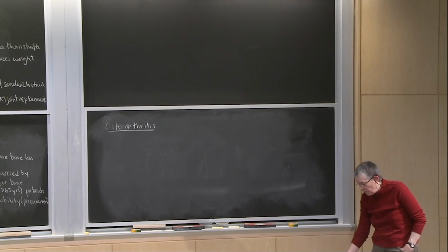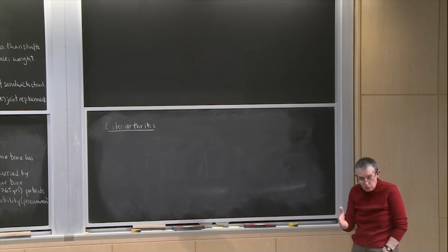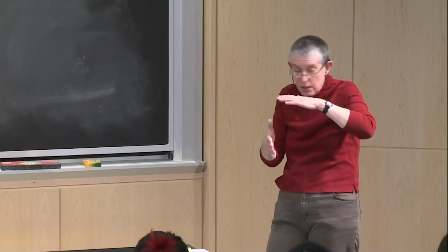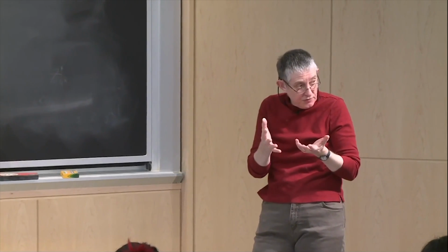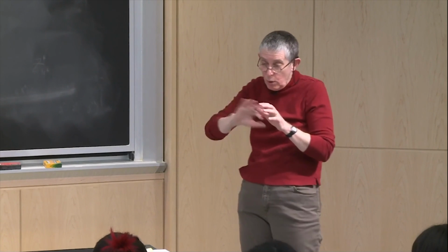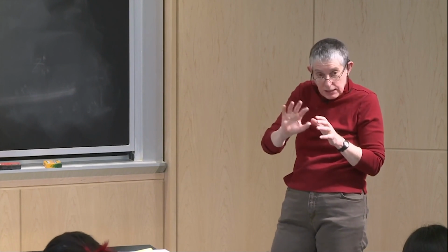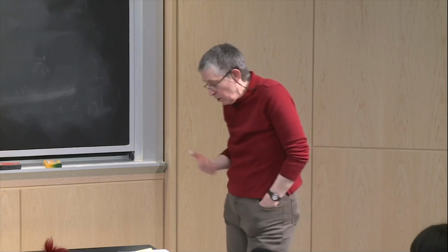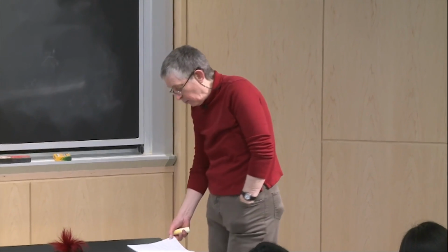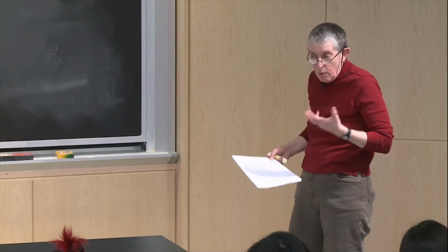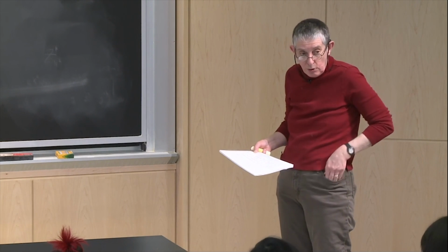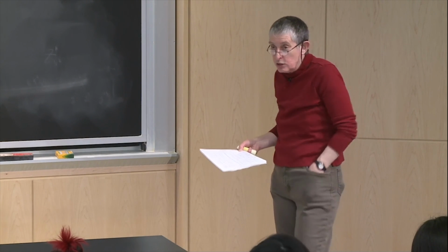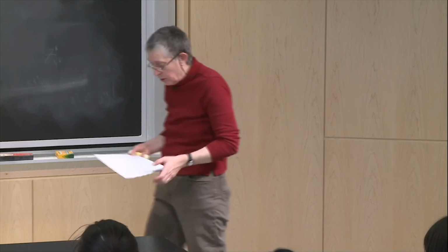You can imagine if you have a fiber composite, for instance, and you're loading it along the fibers, most of the stress is carried by the fibers because they're stiffer. So if you have bone, like trabecular bone that has varying density, the denser bits are going to have higher moduli, and there's going to be more stress associated with that. The modulus of the trabecular bone can affect how the loads are distributed in the cartilage, and that can affect the damage in the cartilage.